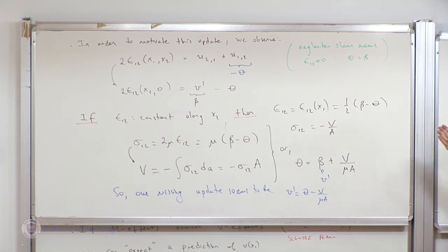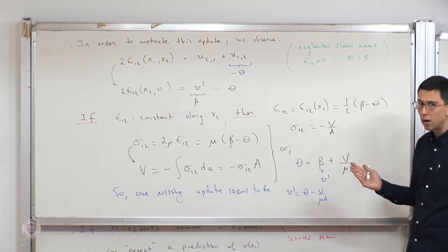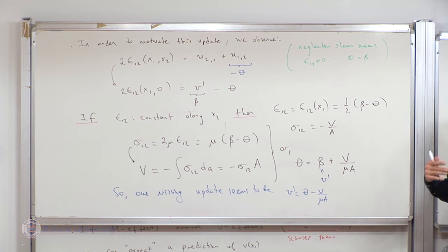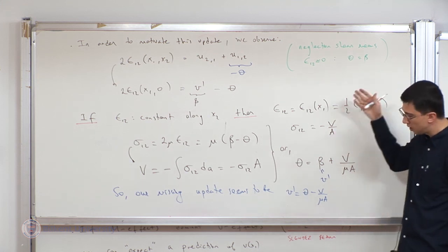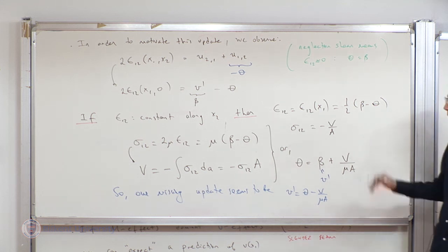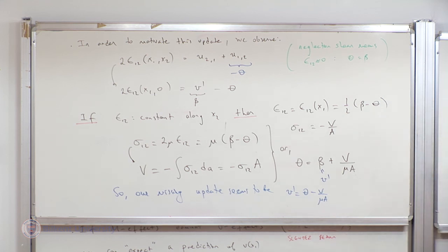Now, whether plane sections remain plane or not, the normal stresses are still equal to minus Mx2 over I. Why is that? Because all of the assumptions that I have used never violate that statement. So normal stresses are always captured exactly. So that's good. I am doing something very well. But now, how about the shear stresses? Am I capturing that correctly?